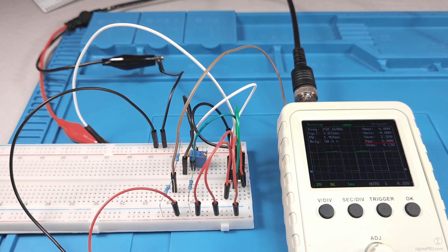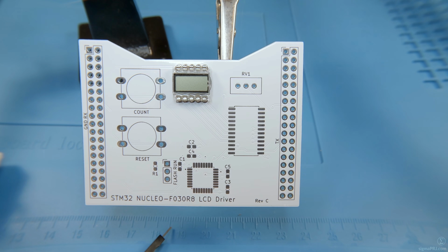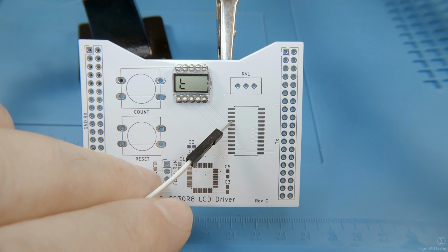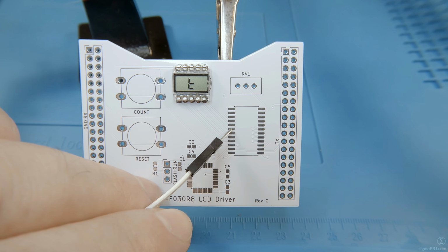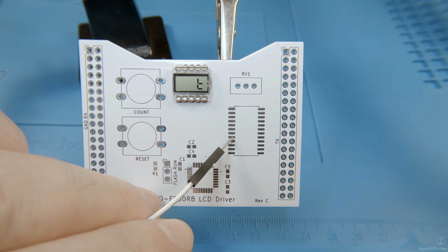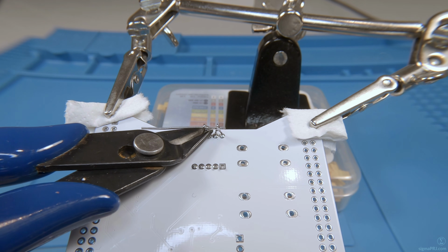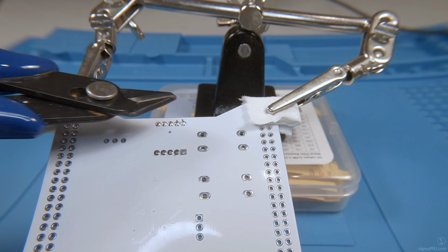Peak-to-peak amplitude is 6 volts here, but in relation to the 3 volts common line level, it is varying between -3 volts and +3 volts, which is perfect for our LCD to drive the segment. All common lines are connected to 3 volts output now, and whenever we are trying to feed square wave into a specific signal pin, we can see that corresponding segments are getting ignited. This way we can make sure that all segments are working fine here. Once testing is done, we can trim unnecessary pins.